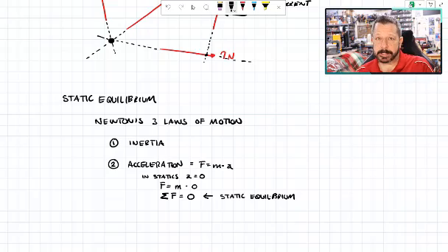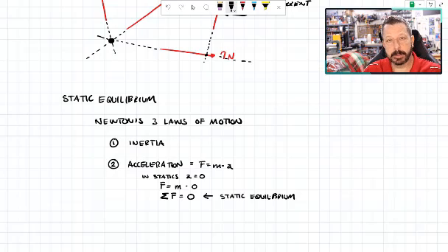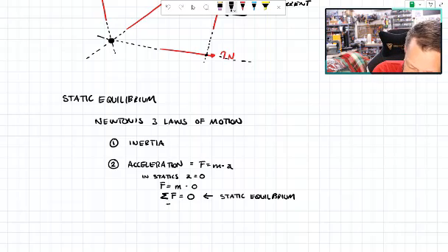And we'll actually break it out a little bit more than that even. The net effect of all the forces acting on an object, if you add them all together as vectors, and they equal 0, then it's in equilibrium. But again, we're not using the vector notation, the IJK, in this course, so we're going to write this equation as 3 separate equations, which are the summation of all the forces in the x direction equals 0.